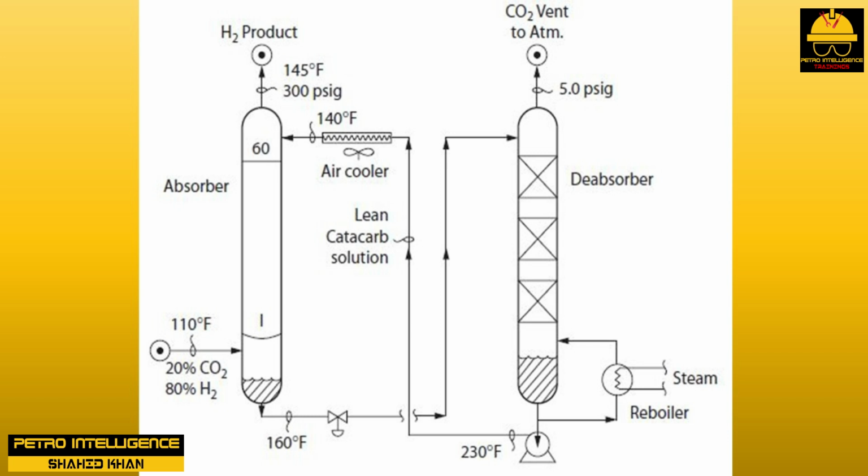None of this made any sense. CO2 absorption in catacarb solution should be favored by lower, not higher, temperatures. Equilibrium conditions for CO2 absorption are always improved by cooling the circulating absorption liquid. The general director of the plant, an American, invited him to a dinner to celebrate the 0.5% CO2.